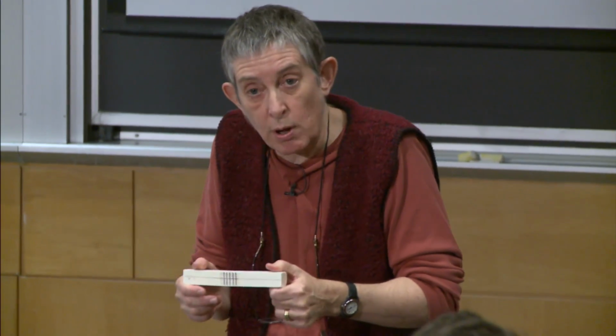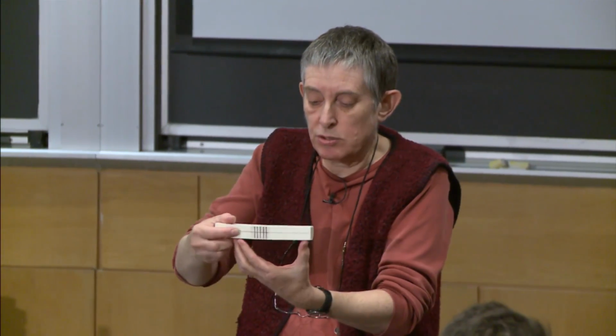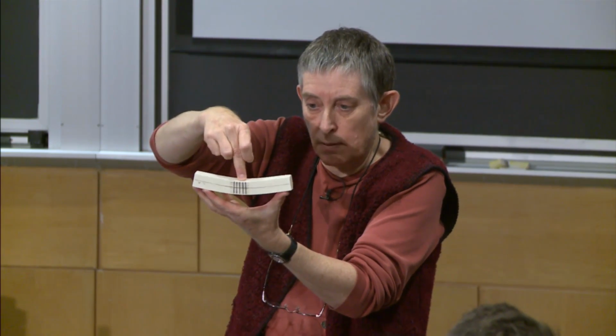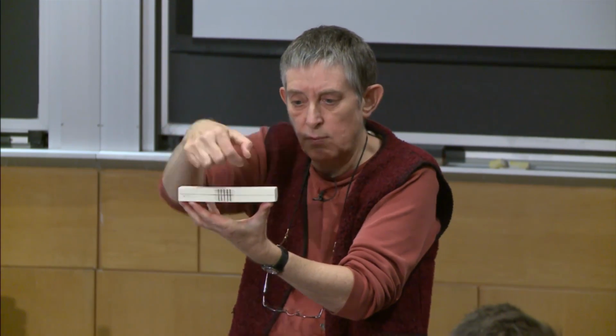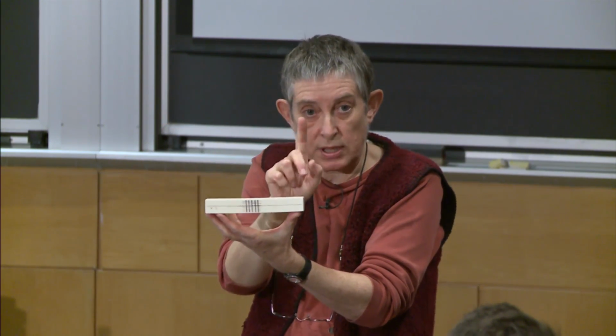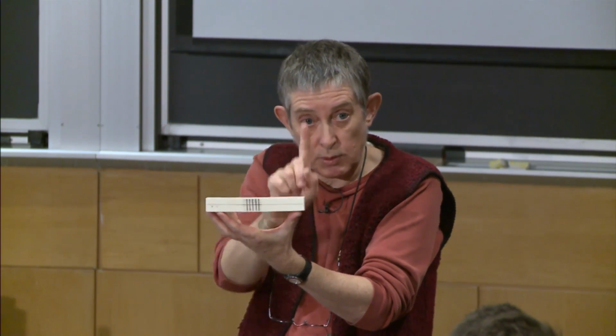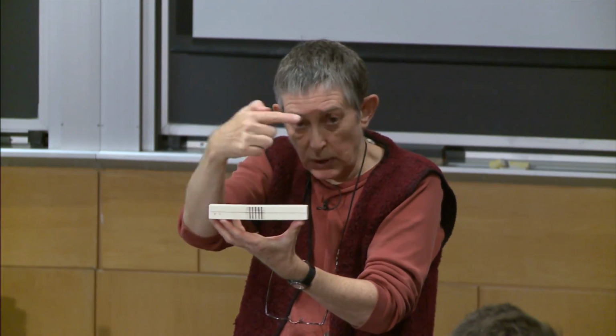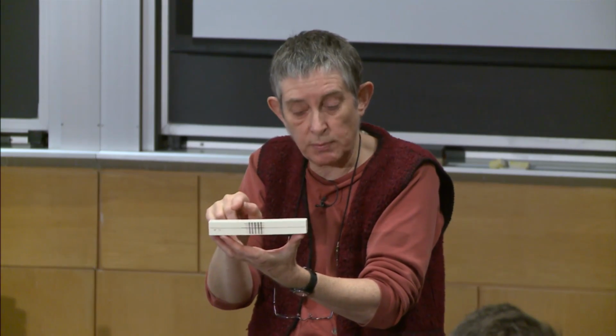So one of the things we want to do is figure out what the stresses are in the beam. Okay? And the stresses are going to depend on the moment at a particular section. So we need to figure out the moments first. And we're also going to figure out the shear forces. So when say I've got my beam like this, and I'm putting a load on it like that, you can kind of imagine if I chopped out a little element here, it would see a force like this and a force like that on the two sides, right? There'd be one this way and one that way, and then there'd be corresponding shears on the top and bottom. So there's going to be shear forces developed along here.